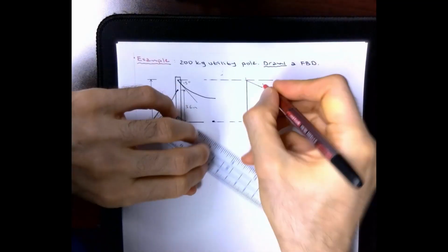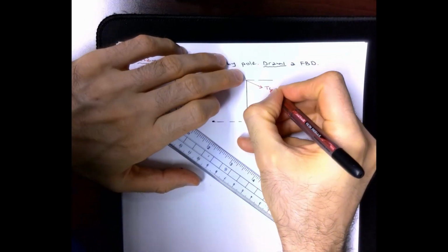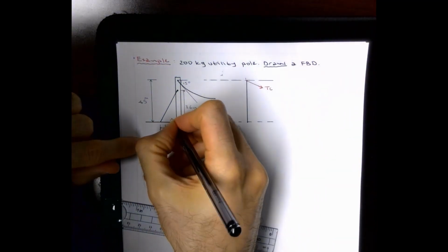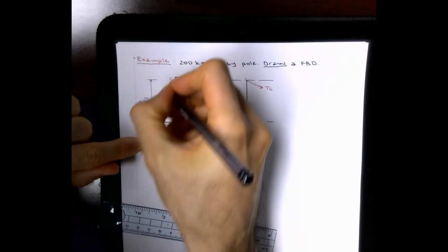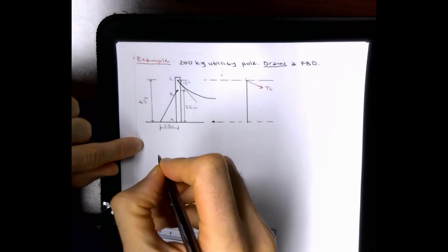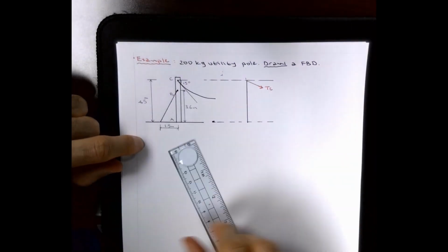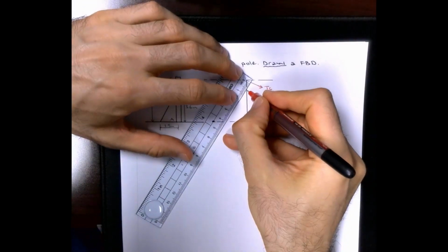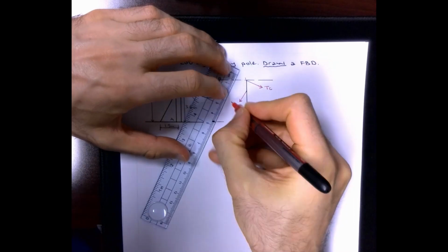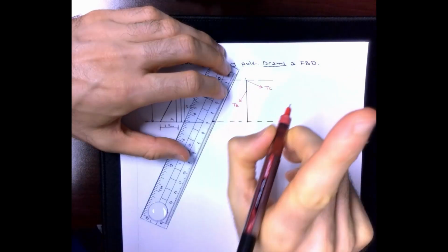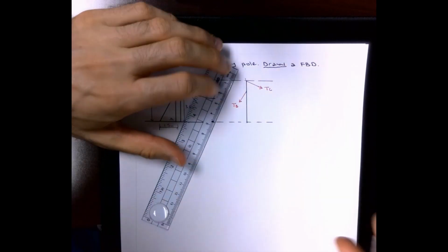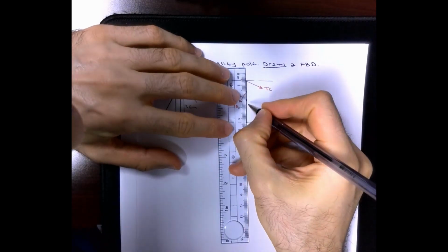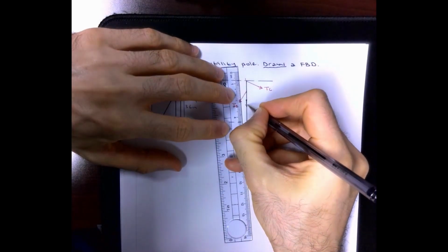So we have this force which is called TC, right? You know, if you want, you can give some names, some letters, A, C, B, right? So that's going to be TC applied at that location. We also have TB, which is from this location. These are cable tensions, only one unknown, right? It's not two unknown. Otherwise, it's going to create more difficulty for you, and you may not even be able to solve the questions if you exceed a certain number of unknowns.